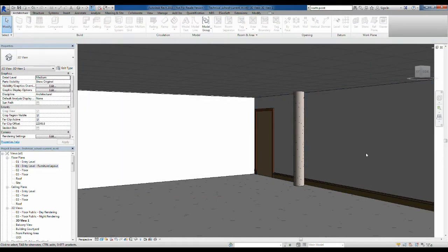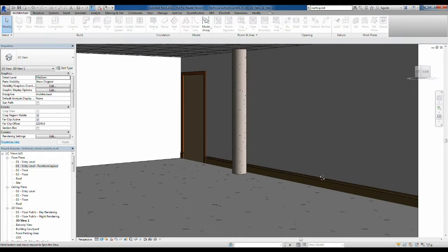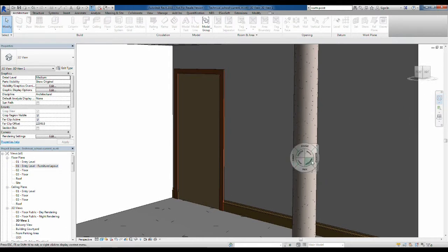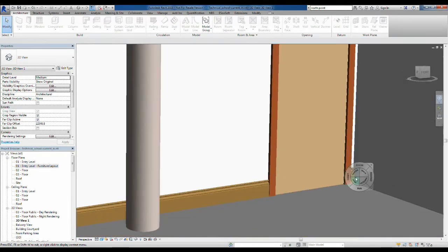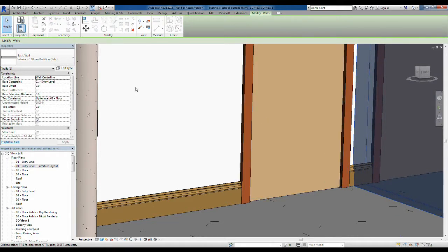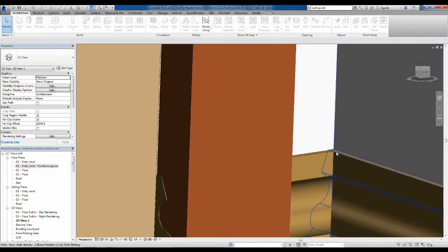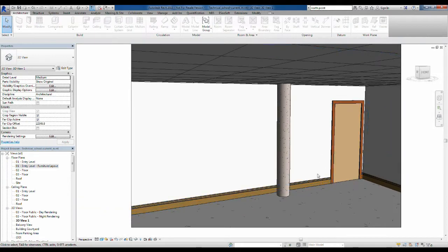We can see I've swapped that wall out now for that particular one with the skirting on. If I just spin round to the other side, whoops, use my look instead. We can see down here, for instance, that I might want to have it join onto this wall. So if I select that wall as well and change that wall to the one with skirting, here we go, you can see how it merges into that particular section there. So very simple tool there.